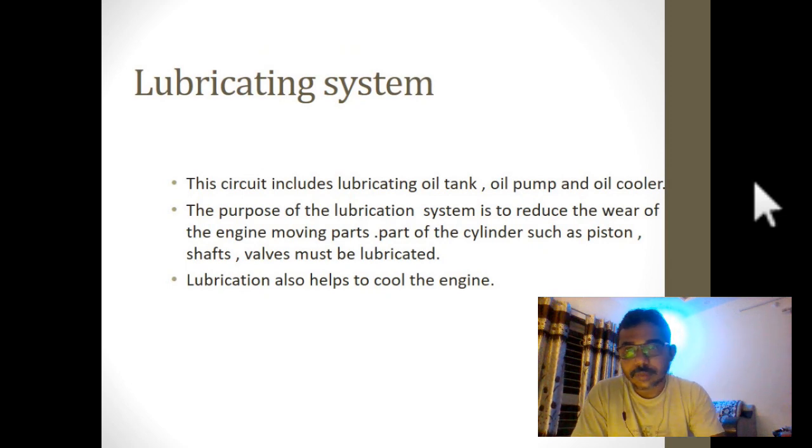Lubricating system. This circuit includes the lubricating oil tank, oil pump, and oil coolers. The main purpose of the system is to reduce the wear of the engine parts of the cylinder such as piston, shaft, and valves, which are to be lubricated. Another objective of the lubricating system is to do the cooling also.